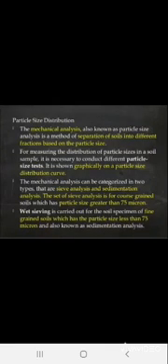So the very first one is your particle size distribution. What is the particle size distribution? In laboratories we use different types of sieves having different sizes, and by arranging them in descending order, from upper to lower, we sieve the soil through the different sieves. After that we collect the portion of soil from each sieve and weigh it, and by the graphical representation we differentiate whether the soil is uniformly graded, well graded, etc.